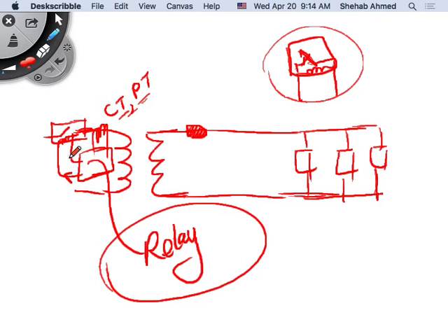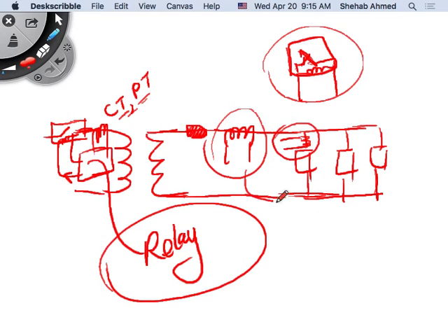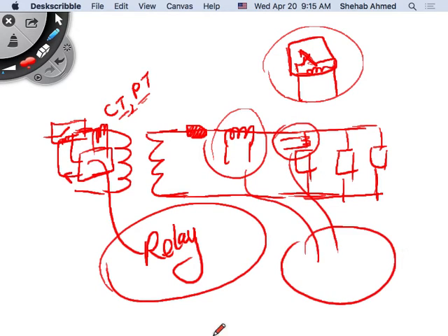If I want to protect a transformer, I have to place the sensors in a certain way. If I want to protect this load, it's different than if I want to protect all of these loads together, right? But I can have this CT and this CT go to the same relay. And this relay can be controlling one breaker out here, right?